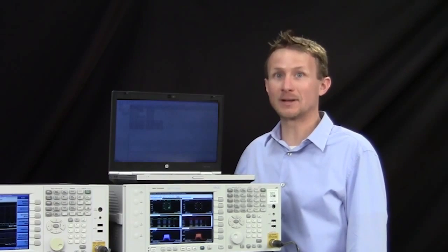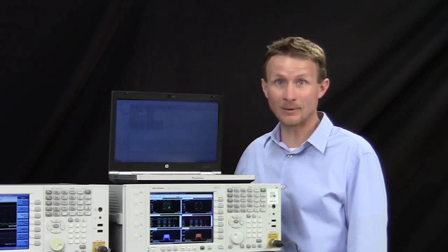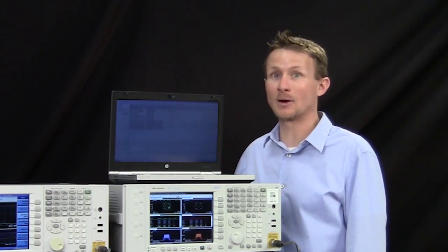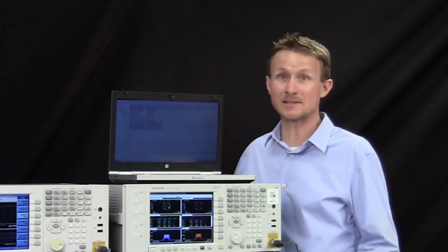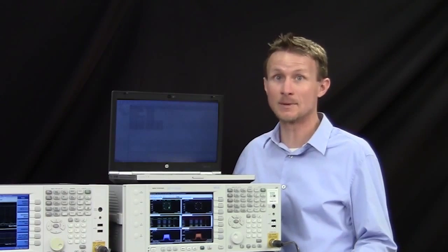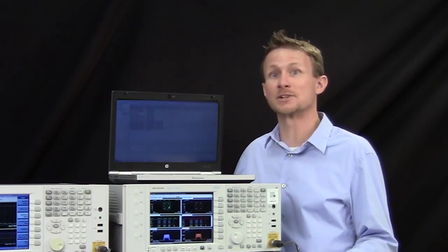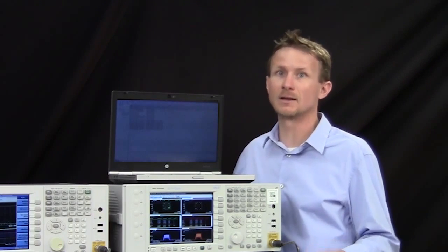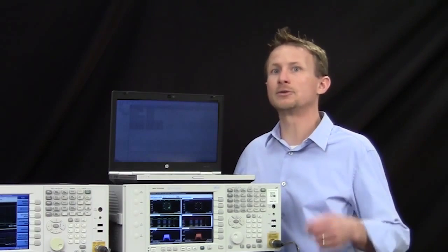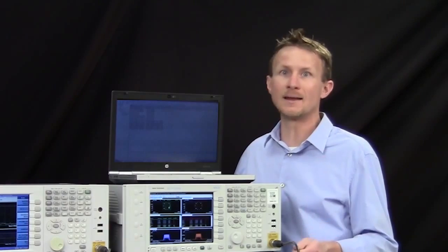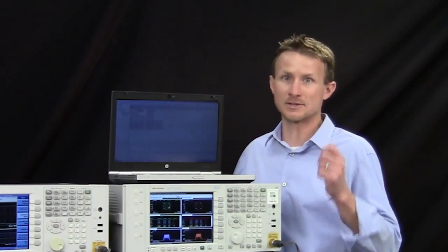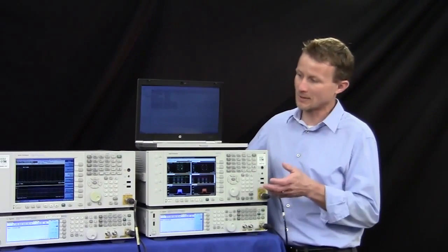From the mobile perspective, we need to be able to receive multiple component carriers, typically at very low power levels and often in the presence of a high power blocker. Additionally, each of these component carriers could be received by a separate antenna and RF subsystem, increasing the possibility for intermodulation distortion, crosstalk, and other self-blocking issues. To troubleshoot and measure system performance, we need to be able to generate laboratory-grade LTE-Advanced carrier aggregation signals. Now let's take a look at our demo setup.